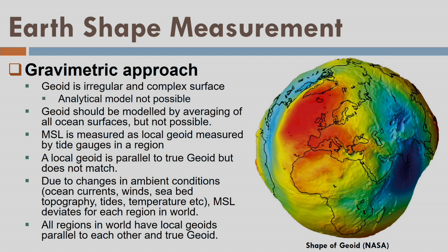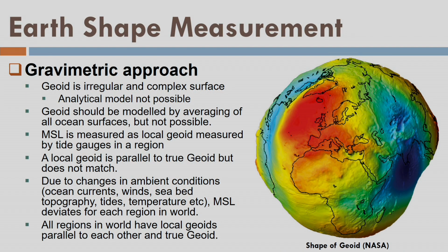Geoid shape means that if I try to draw the gravity potential values of each and every point, that is x, y, and on top of that I put the gravity value, I will get this kind of shape. And hence I realized that it is not only difficult, it is almost impossible to fit a geoid that is unique in nature and that can serve as a single surface for the whole planet. Very difficult, because there are 2 reasons. First of all, the geoid itself is very irregular in nature. Secondly, if you look, there are some sea surfaces and there are some land.